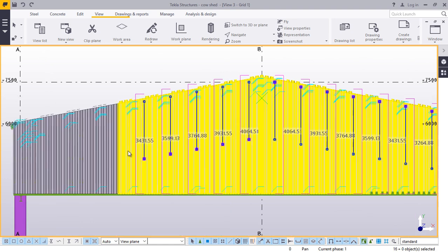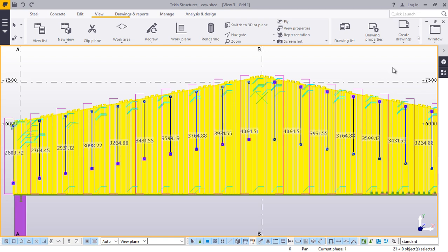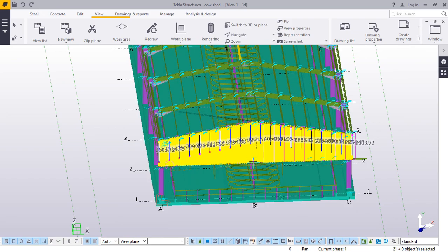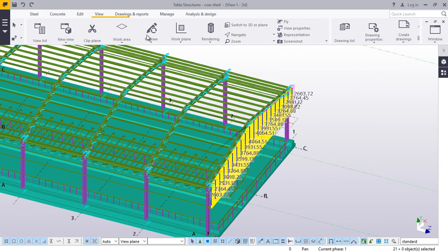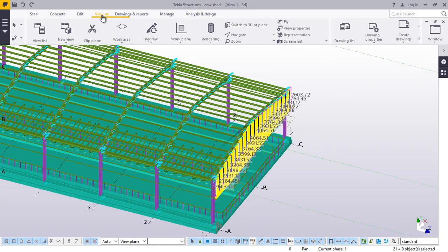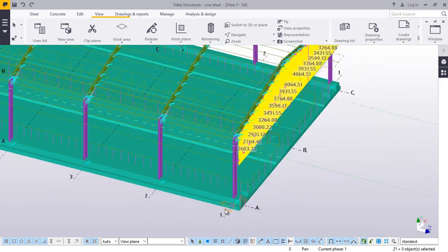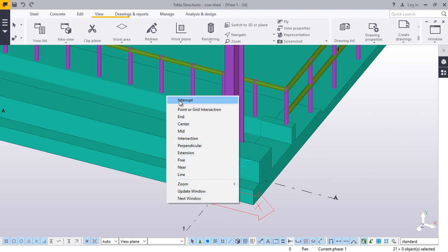Click that, click that, click that, that, and that. Then you can switch back to your isometric view. From here you turn this round, and prior to invoking a mirror command, switch your work plane tool to this plane. Get a point where you can locate it properly.